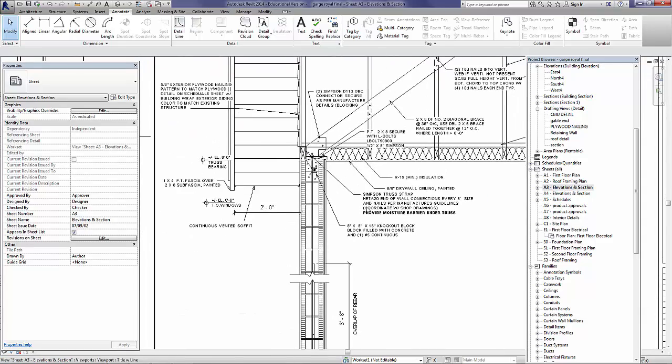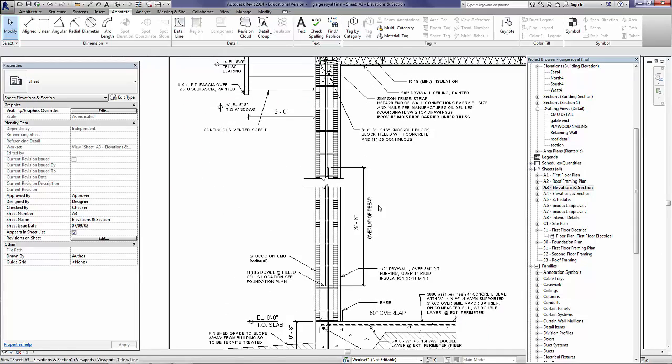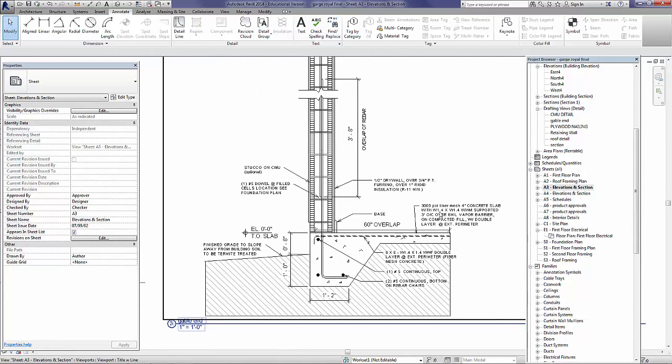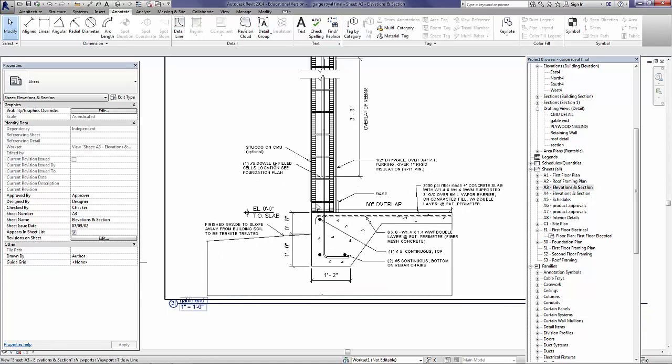You can see how we've got the different types of, in terms of rebar overlap, in terms of types of concrete, different footing sizes here. This is a thickened edge, is what they call this, where it goes down at least a minimum of 1 foot.